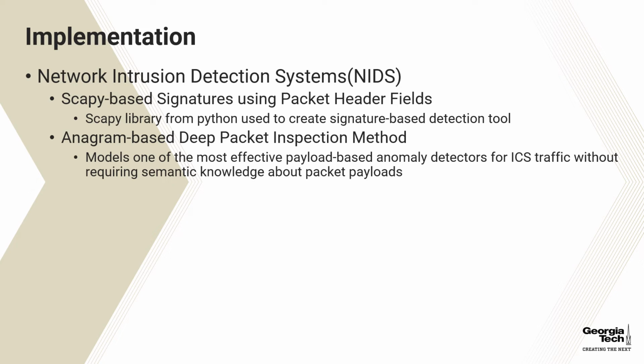In the Modicon M221, it was set to detect if a write request was greater than address E000 and less than FED4, which would mean it contained logic code, due to the logic code always being within that static address range.